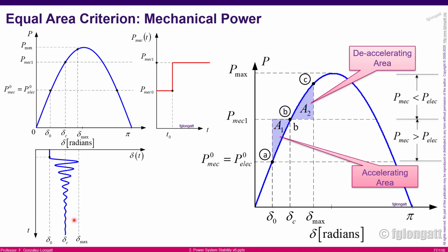Okay, and what I want to show you is here below. You can see what is really interesting. Here is a plot of the power angle. To be honest, this is the solution of the differential equation of the swing equation. The equal area criterion is not meant to do this, but I want to teach you how things are moving here.